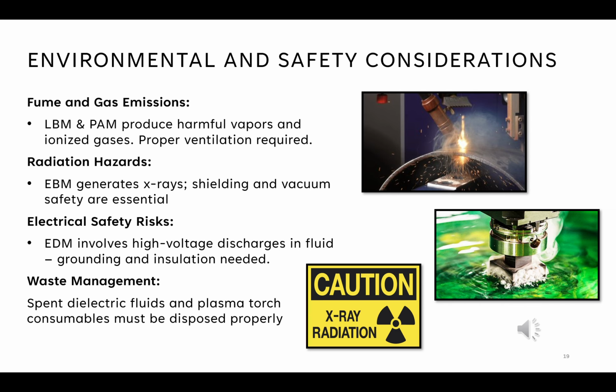There are also heat and fire risks, especially with combustible materials nearby. Operators must wear PPE like heat-resistant gloves, hearing protection, and safety glasses, especially in LBM and PAM environments. Lastly, proper disposal of fluids, electrodes, and consumables helps reduce environmental impact.